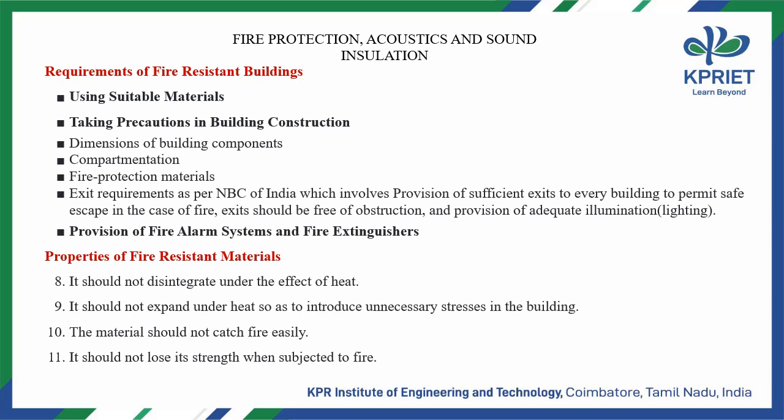Requirements of fire-resistant buildings. Using suitable materials. Taking precautions in building construction. Dimensions of building components. Compartmentation. Fire protection materials. Exit requirements as per NBC of India, which involves provision of sufficient exits to every building to permit safe escape in the case of fire. Exits should be free of obstruction, with provision of adequate illumination and lighting. Provision of fire alarm systems and fire extinguishers.